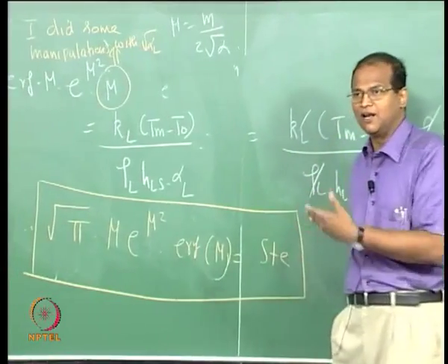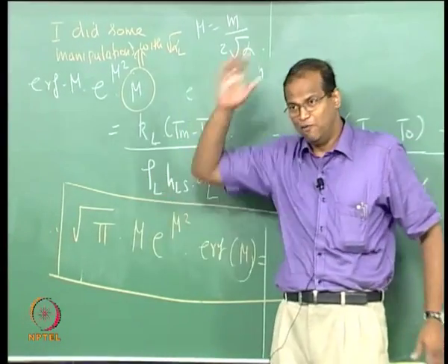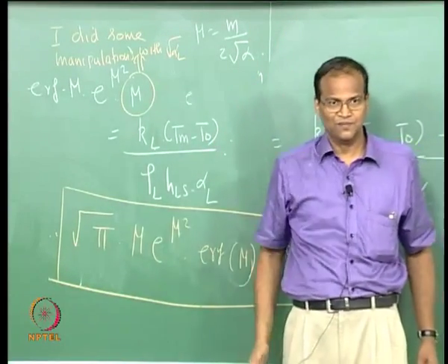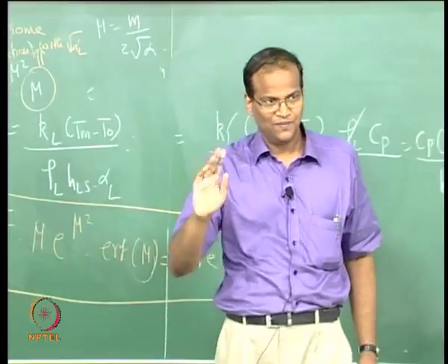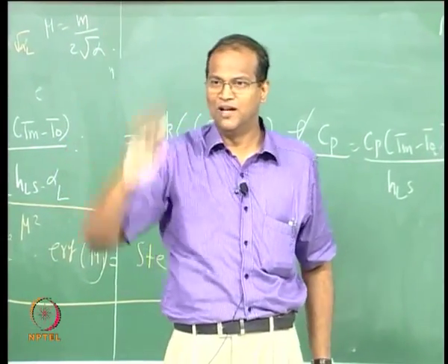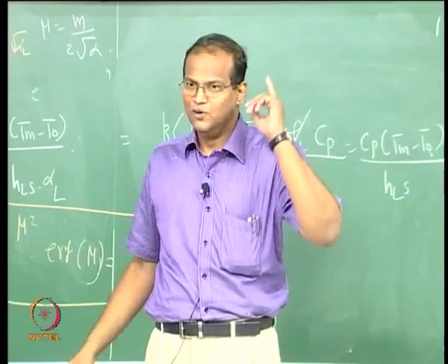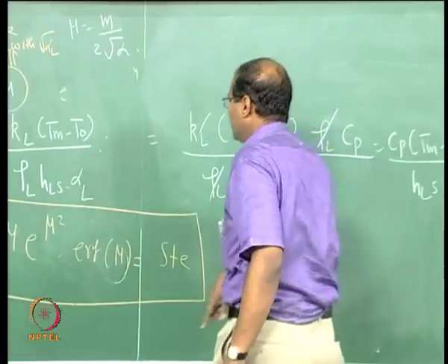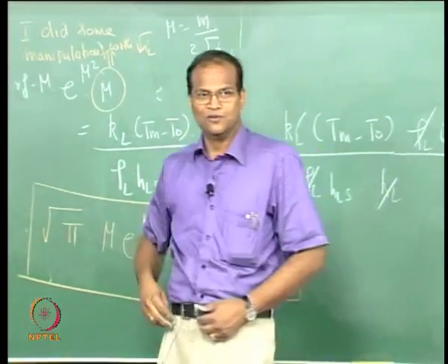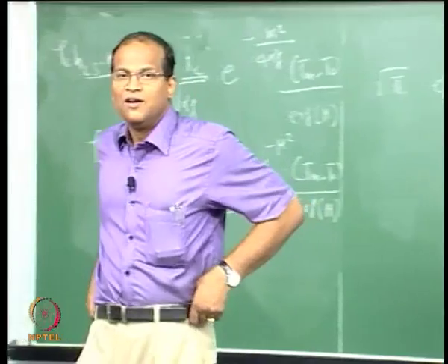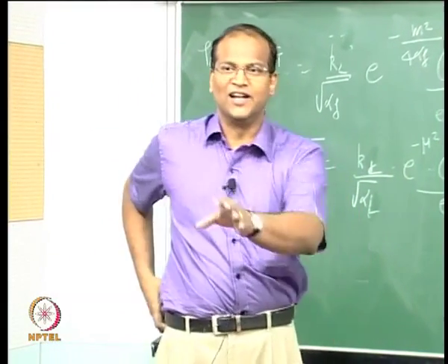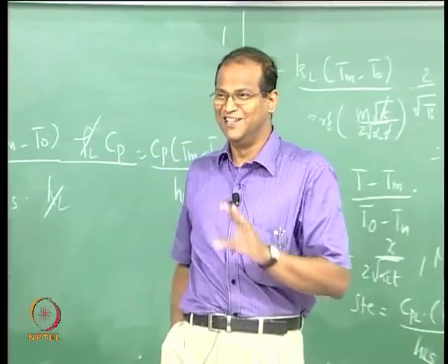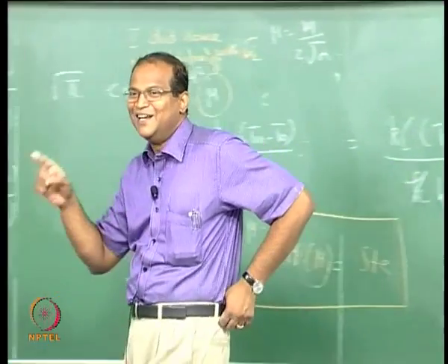Therefore, this equation can be better used if you say, I want this much s. You decide what is the s for a particular time. S is equal to m root t. You decide the s, you decide the t, you will get the m. From there, you will get the mu. For that mu, you find out what Stefan number you have to use. From that Stefan number, you can find out what should be the T naught for you to get that melt front. How much heating must be applied at the left side. This is the better way to use this equation.